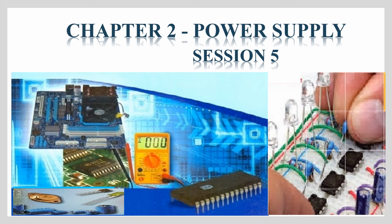So we have seen in that the blocks: transformer, rectifier circuit, filter circuit and the regulator circuit. We have seen that there are two types of transformer, step up and step down transformer. In a regulated power supply, we use a step down transformer followed by a rectifier circuit. The main function of the rectifier circuit is to convert the bidirectional AC into unidirectional DC.